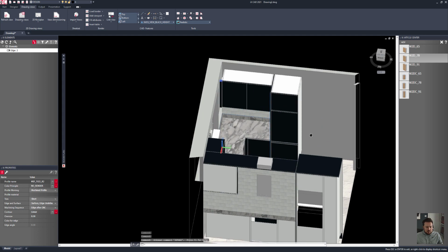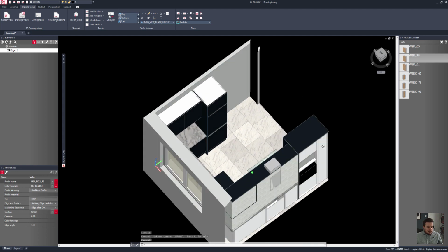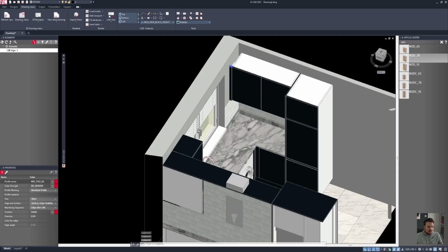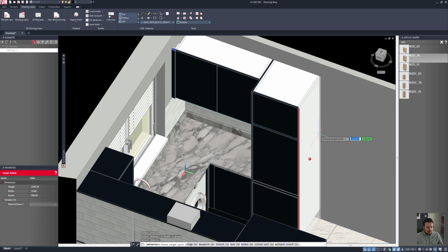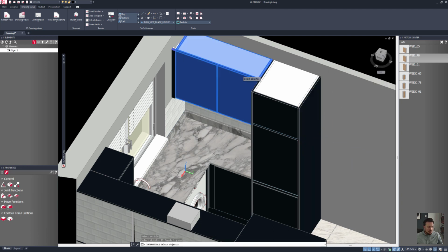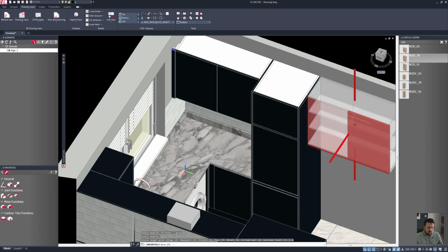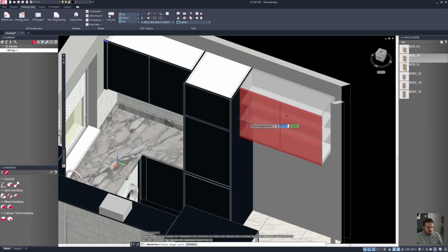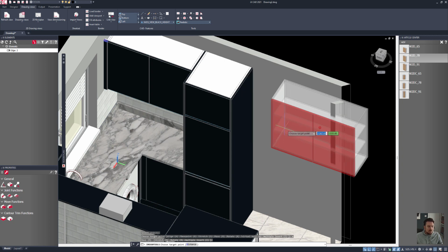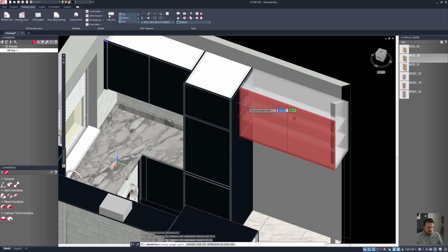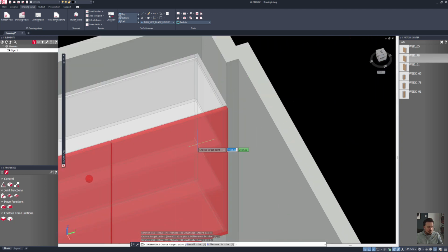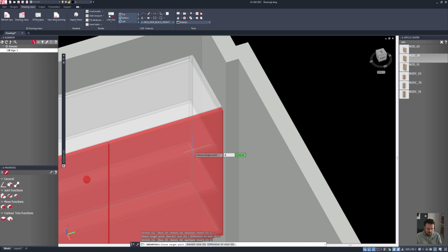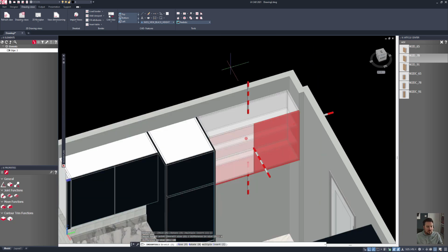Now I want a little bit of a breakfast bar area in here because it's going to just provide somewhere to sit on this side, and I might just copy that wall unit across. So let's get another one of those panels over onto this side, copy this product over. So let's move you, and I need to actually stretch this to the nib on this side, like that, and then maybe just come off that nib a little bit, just because I don't want it to be a dead size. So I'll say a difference of -20 mil coming off that nib.